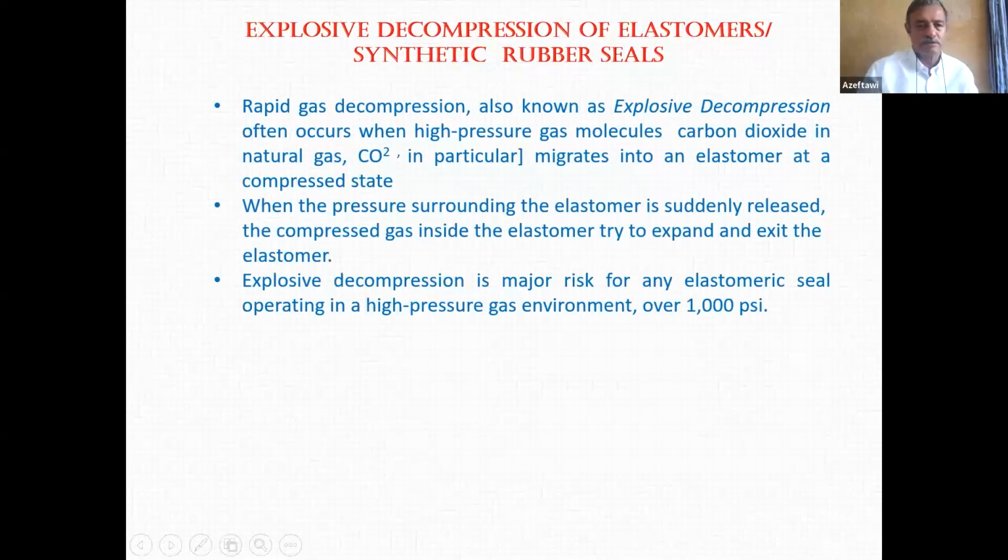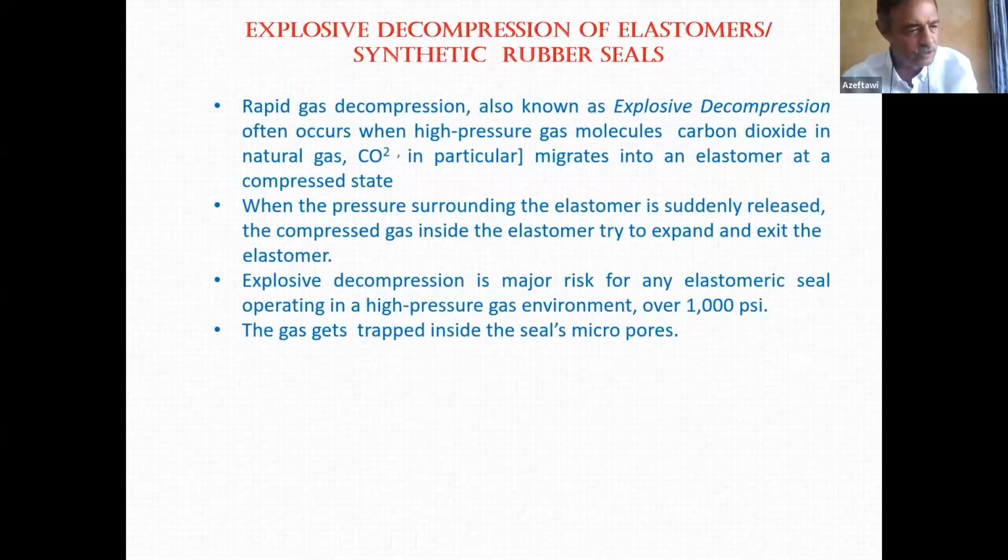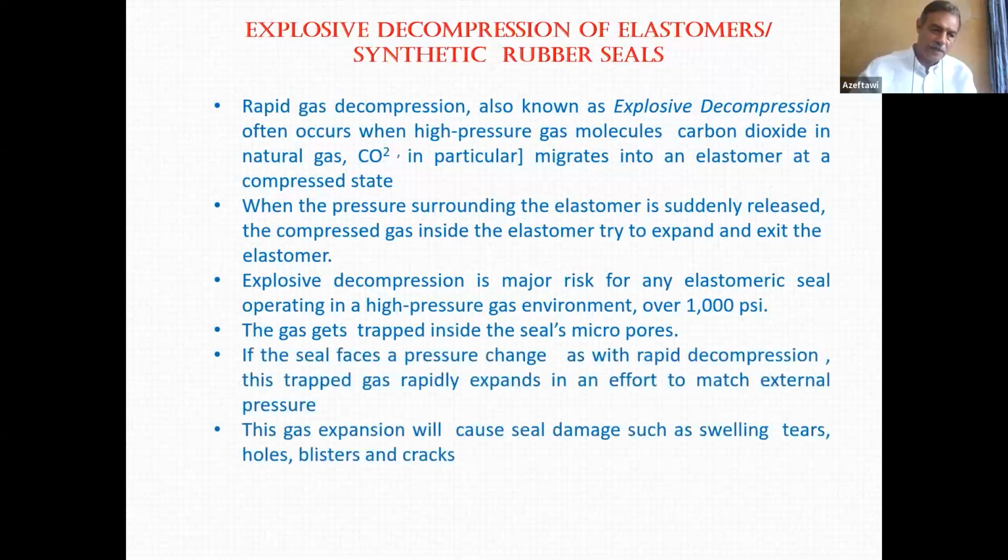Explosive decomposition is a phenomenon that happens to all your rubber elements which are exposed to gases. Rubber, although you think it is solid, absorbs gases. It absorbs gases up till saturation.